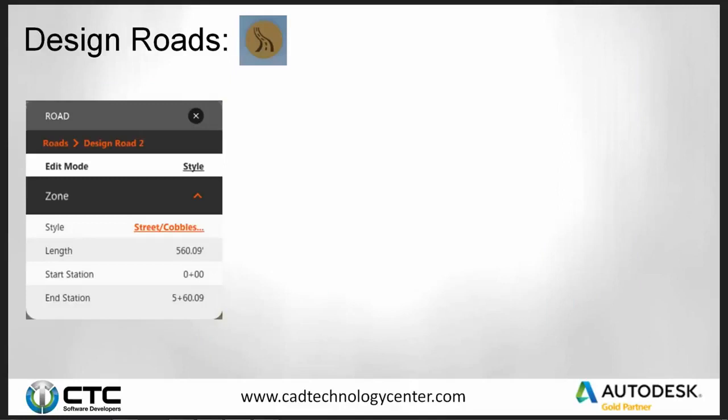I've been mentioning design roads, and those are those 4 roads. In the suites, you have nothing but create roads. So it'll put a road out there, and it will follow the contours of your terrain. But when you bring it into Civil 3D, it comes in as a polyline. Design roads within the 360 will actually, when you bring it into Civil 3D, come in as an alignment and a profile. So I've done most of my work for me in Infraworks in Civil.